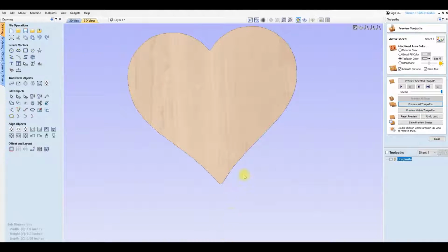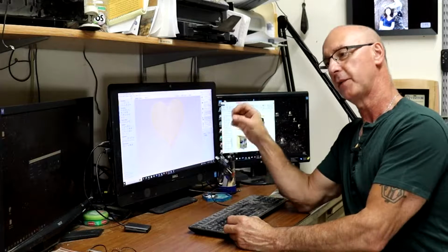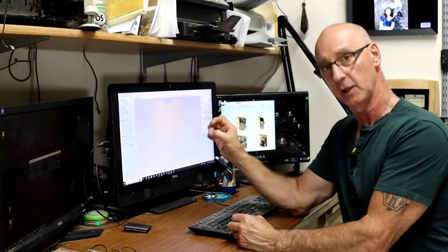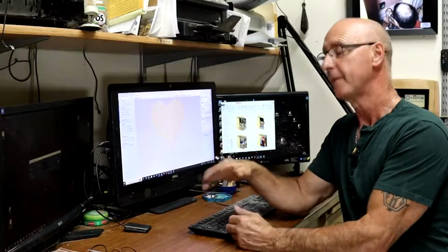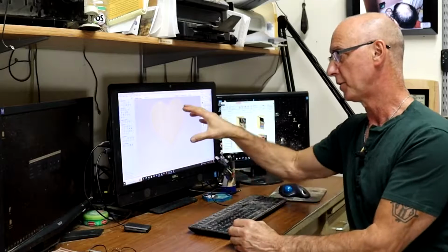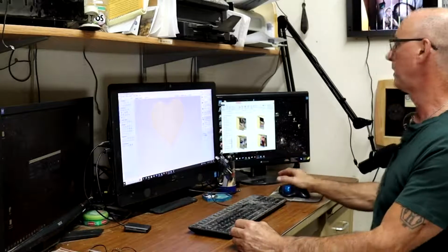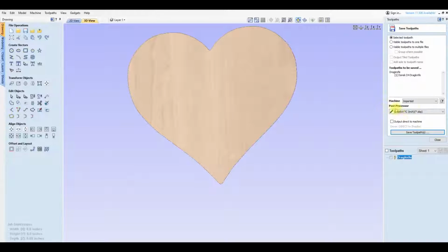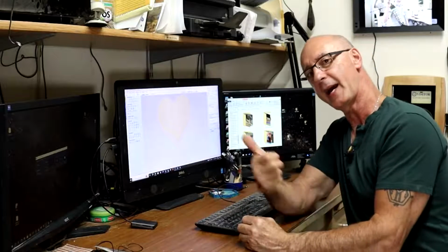It's very simple though in a case where the turns that the drag knife has to make are large enough. It's very simple to just do this with a profile toolpath and make our cuts. You need to look at the specs for the drag knife. The radius it's capable of turning is provided. So if your drawing fits within that, this is a simple way to do this. Here, we're going to be ready to go once we save our toolpath, go through the post processor, and from there, we can head out to the CNC and watch this get cut.